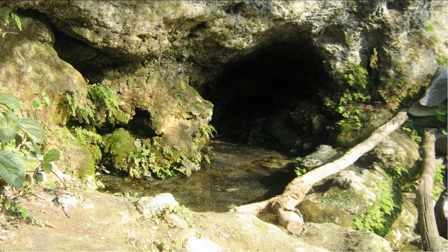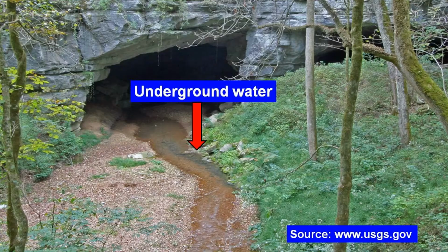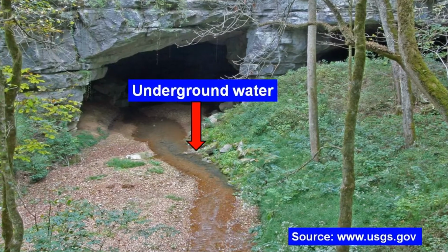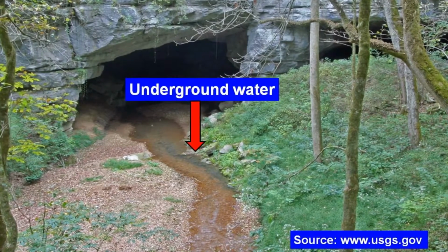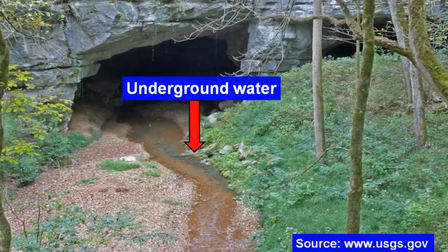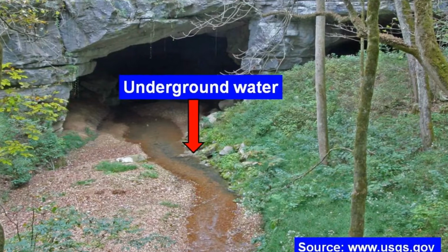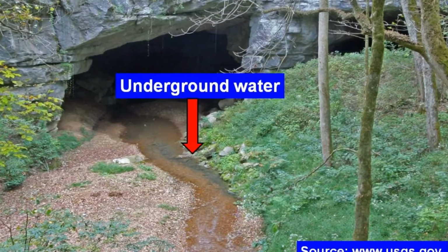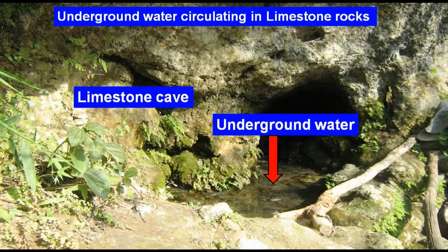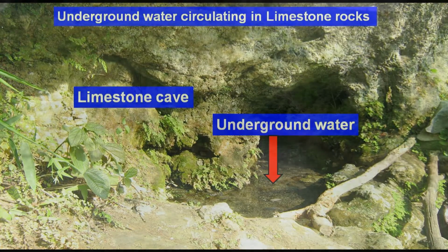Groundwater is defined as water beneath the surface of the earth. Groundwater commonly occurs as water that fills pore spaces between mineral or rock grains in sediments and sedimentary rocks. It also exists in cracks and fractures in crystalline rocks such as granite or limestone.